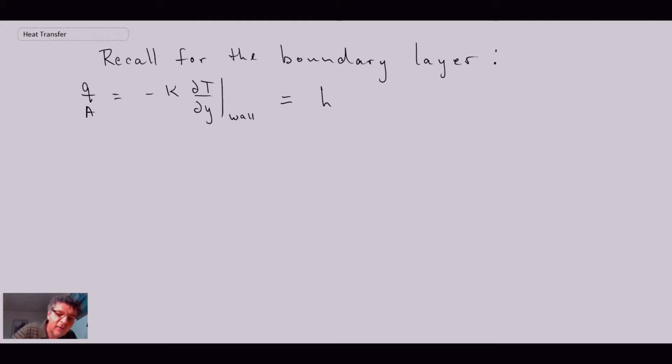So we can use Fourier's law right at the wall, and then we equate that with Newton's law of cooling. We know the temperature profile from the Blasius solution coupled with the energy equation. We can take the derivative, and everything else in this equation is known. It's an isothermal plate, we know the free stream, and we know the thermal conductivity of the fluid above the plate. With that, we can determine the convective heat transfer coefficient h. Writing out the equation, it would be expressed this way.